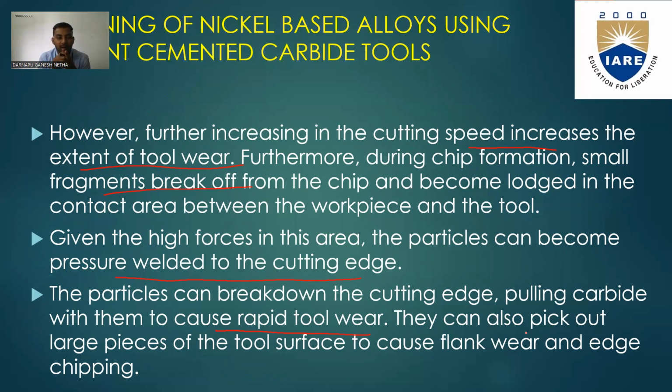Then the fragments break off, and chips from the fragments also break off, and these particles get lodged and contact the workpiece. This contact between the workpiece and the tool causes rapid tool wear to happen.